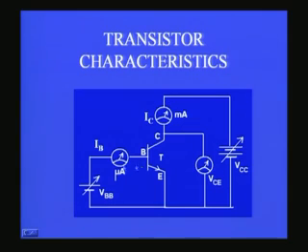It is in milliamperes. The base current meter is in microamperes, and then you have also got a voltmeter which is connected between the collector and the ground or the common terminal, which will measure the VCE, the voltage between the collector and the emitter junction. Because the emitter is grounded, this voltmeter will read the voltage between the collector and the emitter. Now, this is called common emitter configuration, and if I find out the relationship between IB, IC and VCE, this characteristic is called output characteristics of a common emitter configuration transistor.